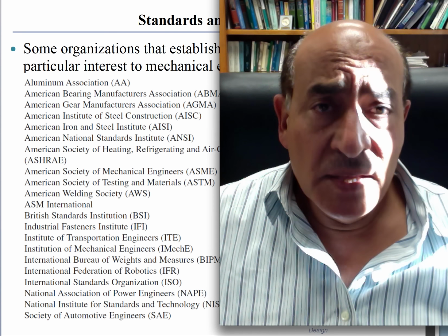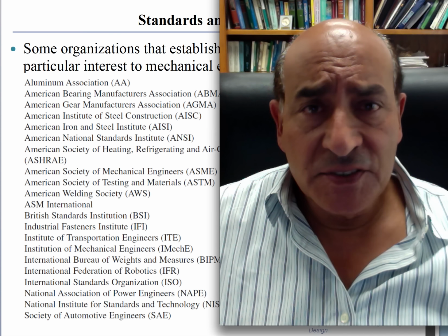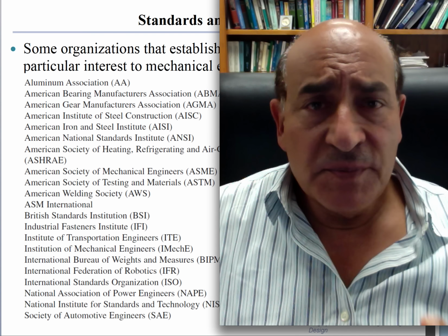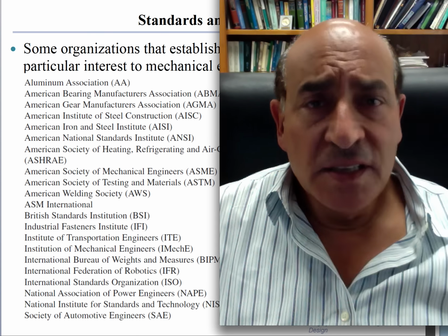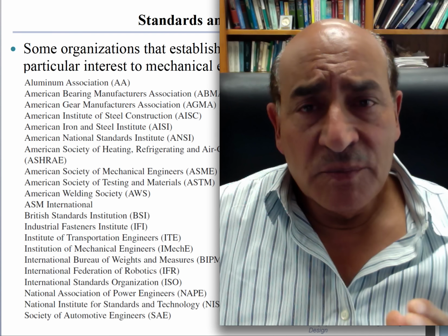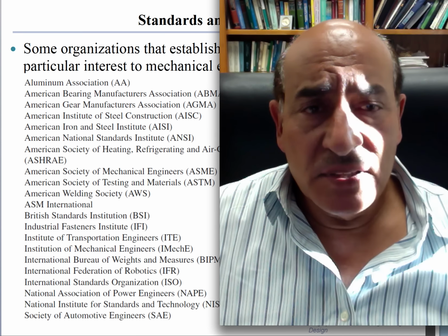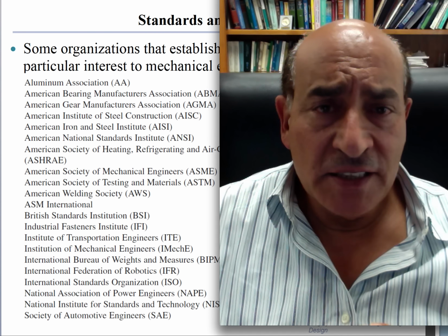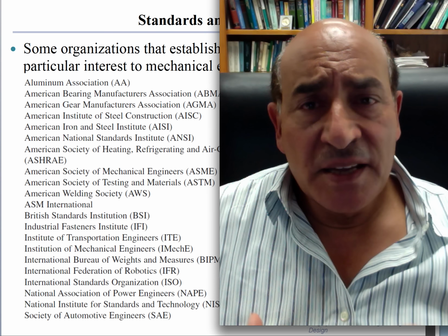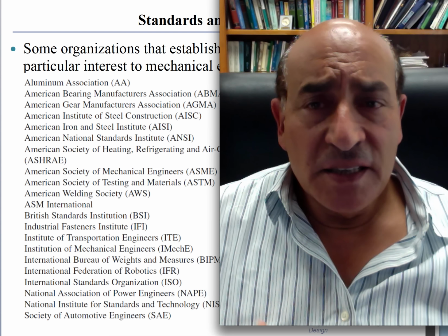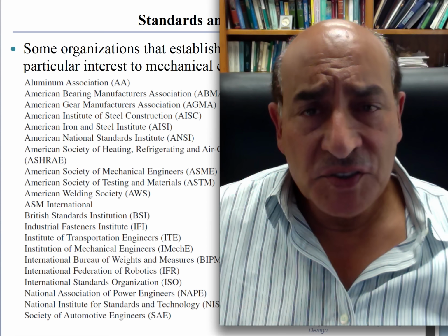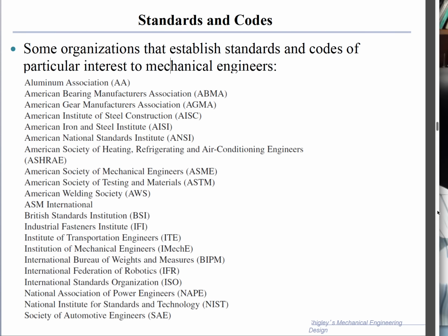For example, in building very large pressure vessels for nuclear reactors and for other applications, there are codes put together by the American Society of Mechanical Engineers, ASME, and the codes are labeled pressure vessel, PV-B, pressure vessel and boiler code. That's a set of voluminous volumes, maybe 6 or 7, that we must consider when we design large-scale pressure vessels. So it's not up to us, but we have to practice. In this course, we will start the process, and as we go on and work in certain applications, we'll gain more and more information and become more and more specialized.